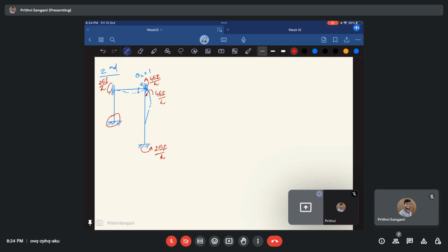So now moment at C is 4 EI by H plus 4 EI by H. That is 8 EI by H. Now moment at B is 2 EI by H.